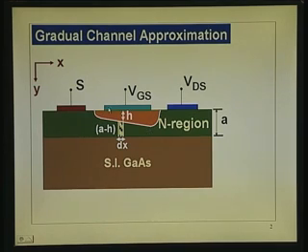But as VDS becomes larger, current becomes larger. We saw that ID is proportional to VDS and it is linear initially. Now, how long will it be linear? That is what we want to see, and what happens if we keep on increasing the VDS. As we increase the VDS, the current increases and the drop increases, and if the drop increases, the potential across the depletion layer changes.